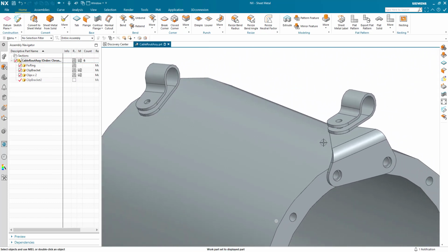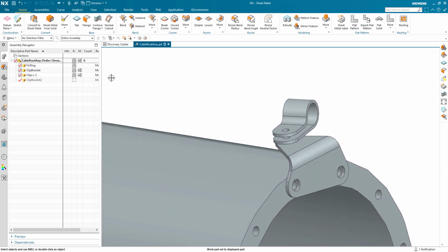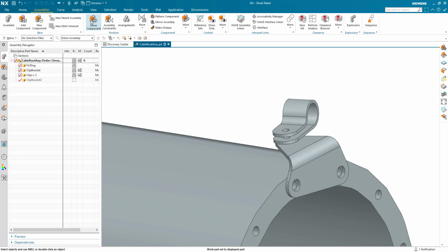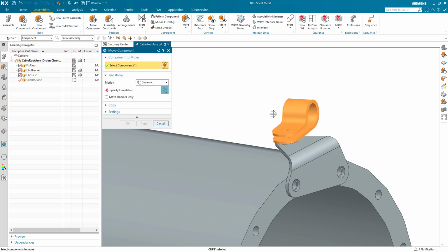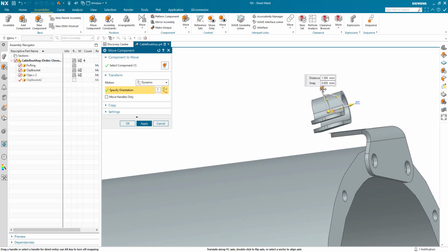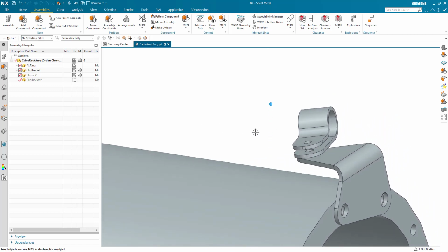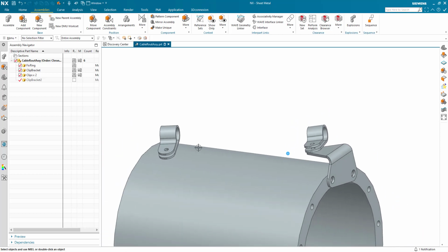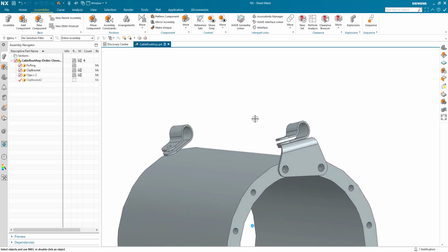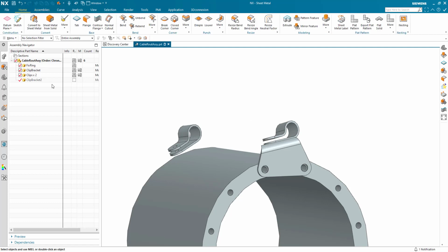Now, the reason for the interpart link, of course, is once that's created, if I happen to move a component, if this clip moves, and maybe I adjust its position and its angle, hit OK, and we can see our bracket automatically updates, and I can do the same for the other end. Let's run through that now to show the process once more, and I'll speed that up.